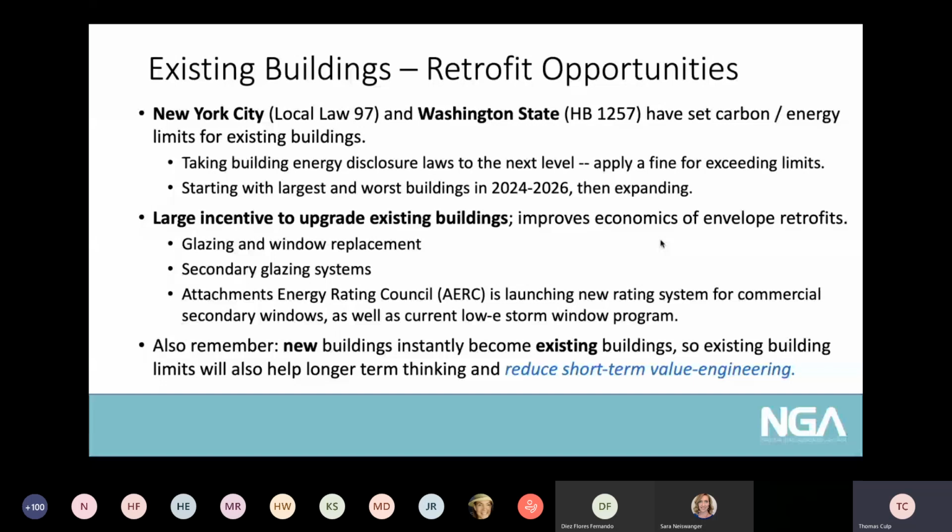I think it's up to our industry to try and push to avoid that. Value engineering is there for a reason, but we need to point out the negatives when you do that. By ignoring the perimeter, the framing and the spacer, are you going to create condensation issues in certain areas? Are you creating other potential problems, moisture problems, things like that? So we have to really push to preserve those attributes. But yes, I would agree that's a true statement, that they're linked.